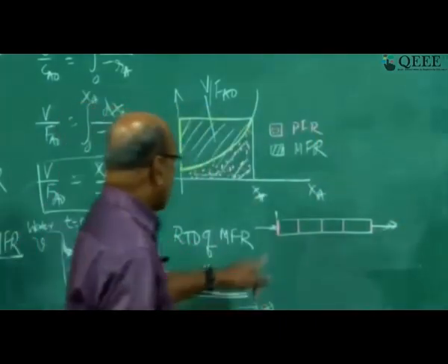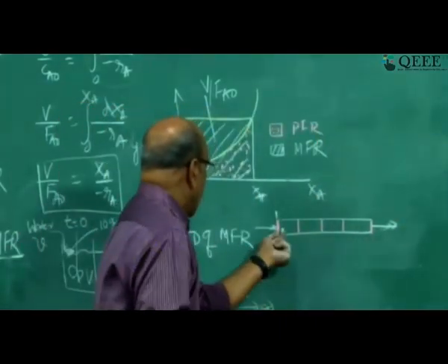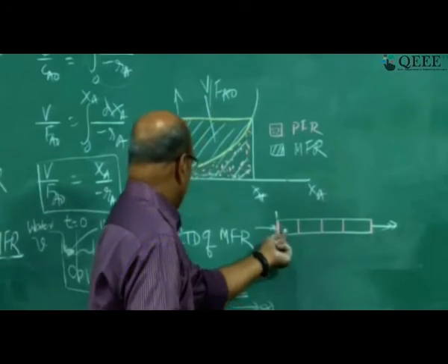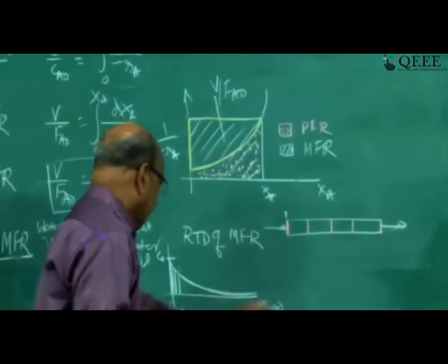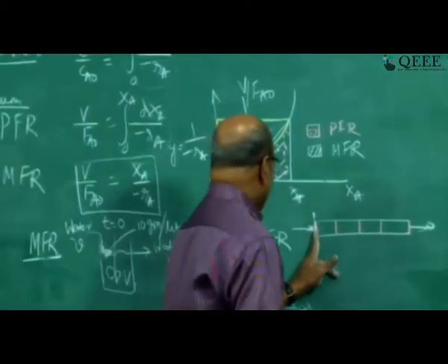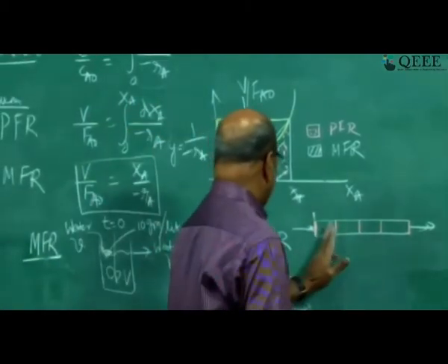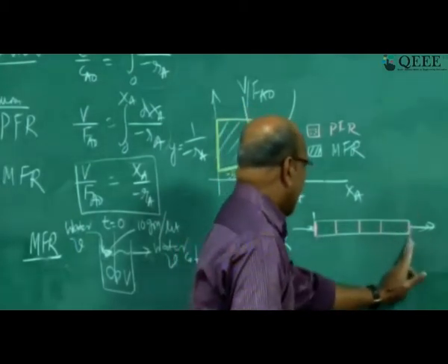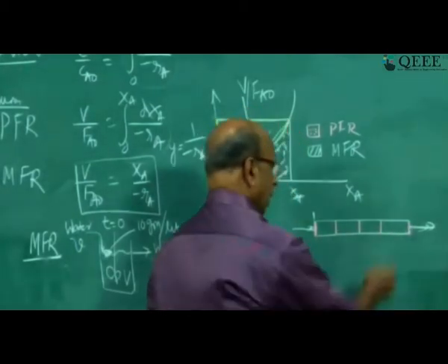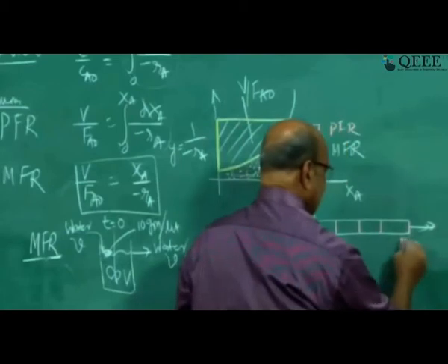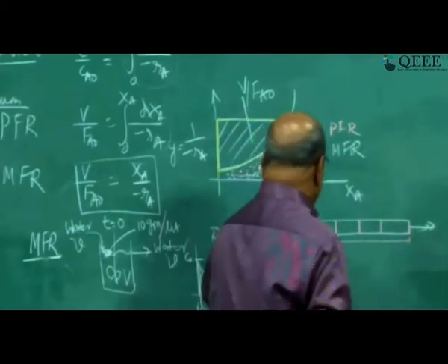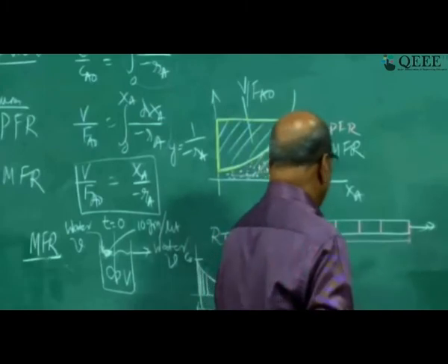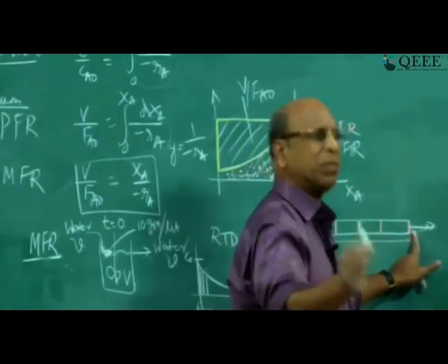Now you see what is the residence time distribution of these red molecules. Like the ink molecules before, here the red color is moving without any disturbance, and finally exiting here with the same residence time. So now each and every particle in this disk is spending exactly the same time.